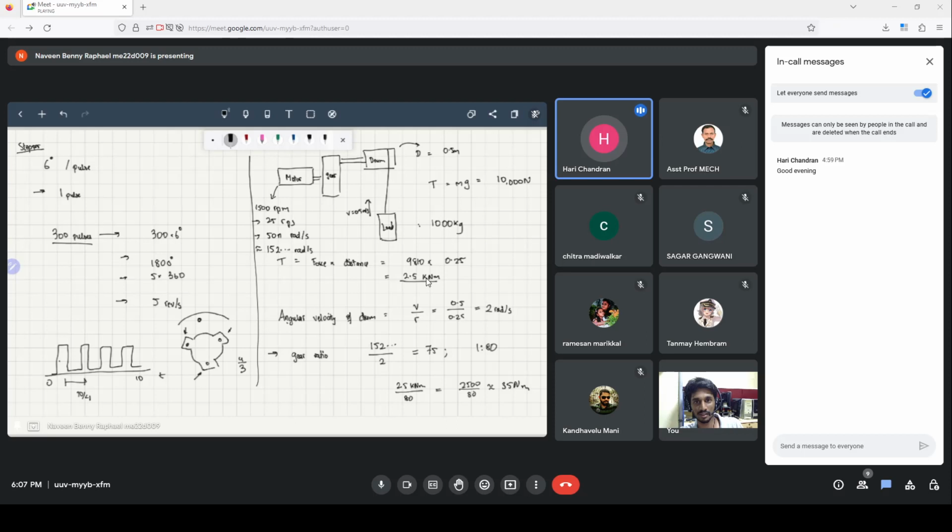Hall effect sensors are specifically used to get positions, so we have to do further data processing to get the velocity from it. Your point is valid in the sense that we cannot directly get the speed of the motor from the Hall effect sensor. That's true. We can calculate it later, but I would recommend that you add this to the discussion forum. You might be able to get marks for this.